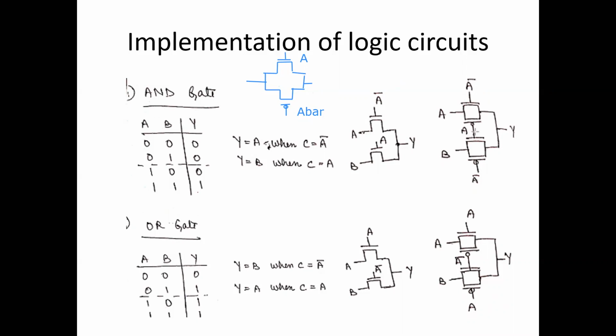See here, this is NMOS. So on the bottom they have written a PMOS. This is also an NMOS. So on the bottom they have written something like this, and they have implemented the P transistor with the bubble. There's a bubble here, and this is A, which means this becomes A bar. If this is A bar, for this P transistor you have to give us A, the negation value. So this is the implementation using TG, transmission gate.